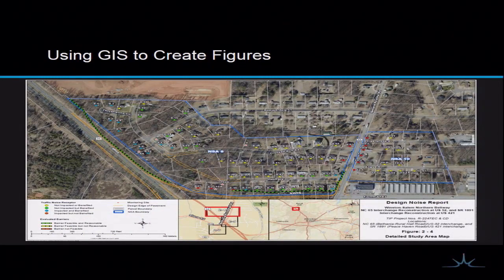So another use of GIS after we're done our whole modeling process, we get certain noise impacts based on whichever DOT we're working on and whichever their criteria is. I think a heavy use in GIS for us as well is cartography. And GIS has helped us streamline a lot of cut sheet mapping for a lot of projects, because I know before, I've talked to folks who have used MicroStation and other mapping services to create figures, and they're doing one figure per area, whereas if I use something like data-driven pages in GIS, I can go through a 12-mile stretch of corridor and have each polygon represent a certain cut sheet and kind of breeze through everything pretty quick.